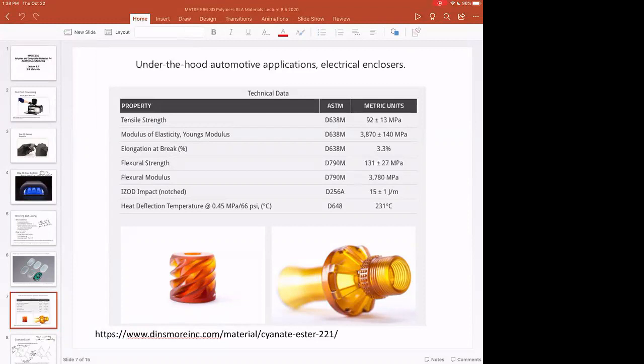So we're still talking about SLA and photopolymers, and remember, we've covered stereolithography in a few different geometries, whether it's top down or bottom up, or whether it's laser raster scanning with a galvanometer and a point source laser, or if it's a DLP style illumination with a digital mirror device, whether it's a continuous lift like CLIP from Carbon, or other printers like the 3D Systems Figure 4 also does continuous elevation, or whether it's a step and wipe like we saw with the Formlabs printers.